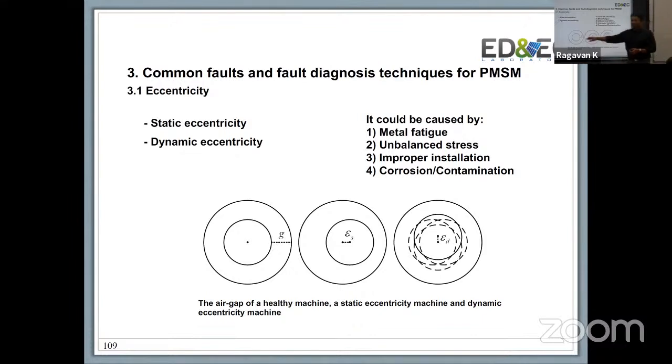So if you look at this, the basic definition of your motor is that you should have a uniform air gap across the entire motor, right? There should not be any variation. And that's an assumption we always make, assuming that the bearings have been mounted properly, that the phase windings have been done properly. One issue, for example, you might have is that you might have wound for certain kinds of machines, or in our case, the concentrated coil, you might have wound it backwards or connected the terminal backwards, which means you will have a flow of flux that is going to go, let's say, downwards as opposed to towards the back iron.